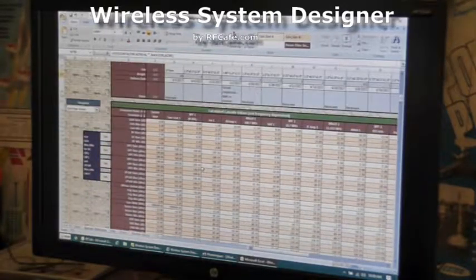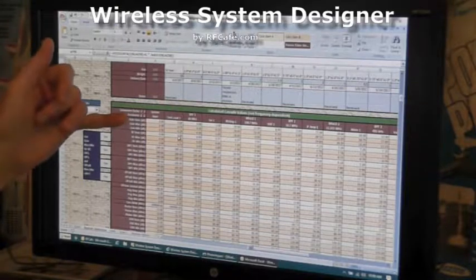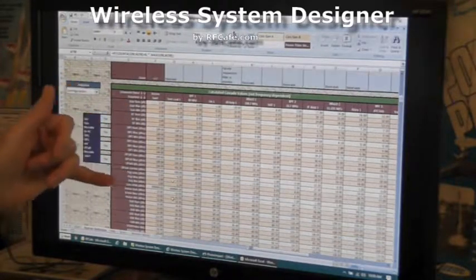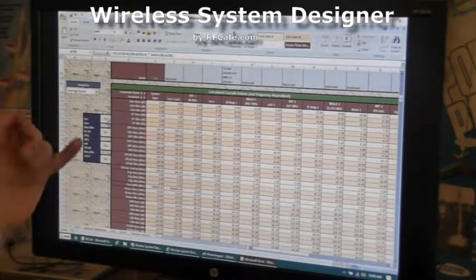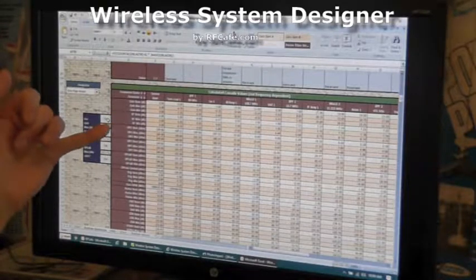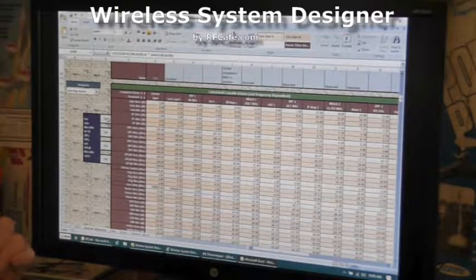All the cascaded values are calculated down here. Notice all the cells are brown, which means you can't monkey with them, and as long as you leave the worksheet locked or protected, you can't accidentally overwrite anything. I report the nominal and then the max and the min for each one of the values. And what I've done over here is, some people, when they're looking at the minimum and maximums of values, the noise figure, intercept points, might not want the gain variation included in that calculation.